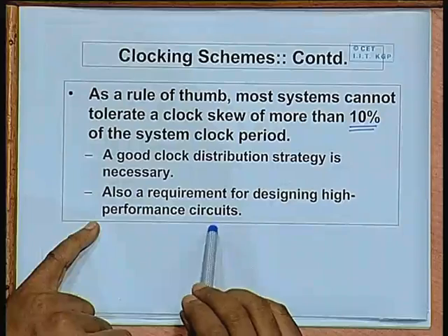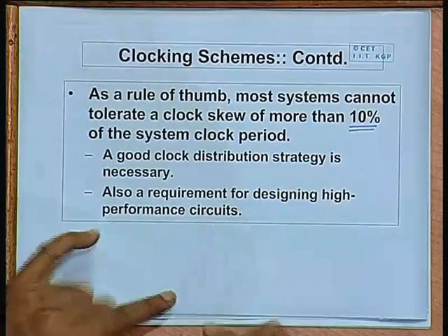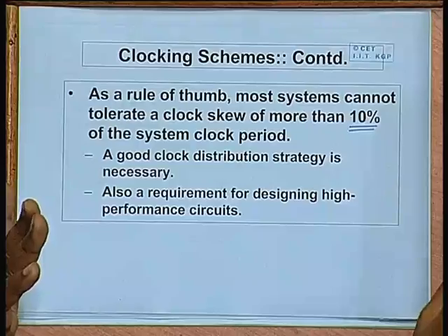Here is another thing I am mentioning. Since the clock distribution is so important and we want minimum skew in the distribution, it is often the case that the entire clock network is routed on a single layer, because as you switch from one layer to the other through the via connection, there are some additional parasitic effects which will incur additional resistive and capacitive loads.